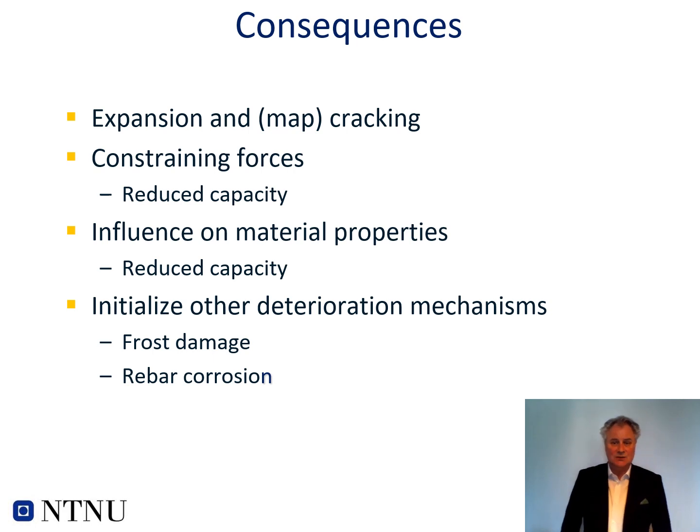The consequences of this reaction are that you get some expansion and map cracking in the concrete. You get some constraining forces which could reduce the capacity of your concrete structure. And it will influence the material properties of the concrete itself, reducing the capacity.